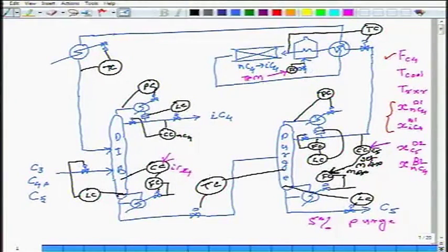What I would say is reduce the composition set point so that there is less C5 circulating around, and so the flow rate of this recycle stream or the distillate from this column will go down. Then the temperature here will go down, right, and I can suck in more. Yes or no?